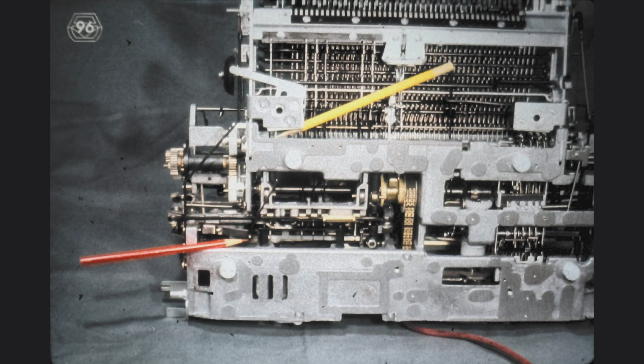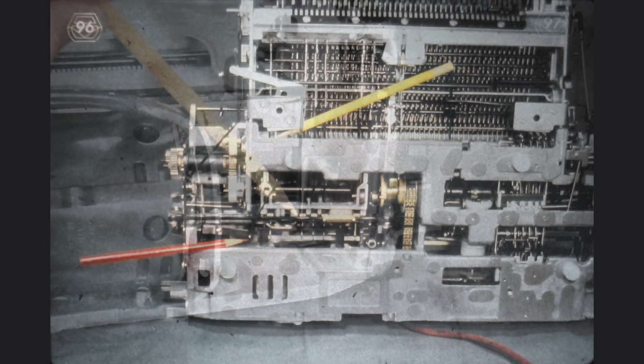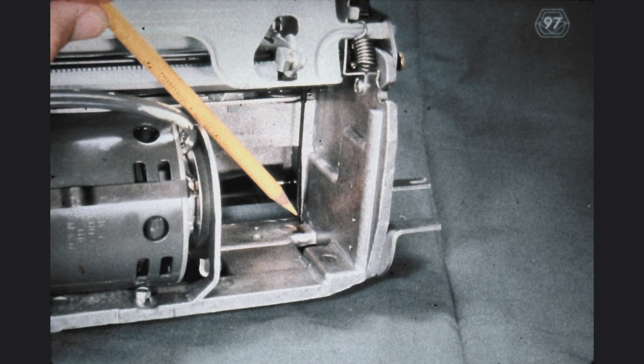This clevis allows us to adjust the length of the link connecting the tab keylever to an intermediate crank at the point indicated by the red pencil. After the rest position of the tab keylever has been established by the adjustment of the keylever up-stop, the link shown in the previous slide must be adjusted so that this intermediate tabulation crank does not touch the base of the power frame with the indicated arm. This arm holds the tab torque bar link. Take a moment to complete this adjustment before continuing.